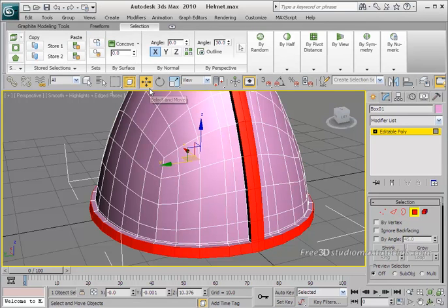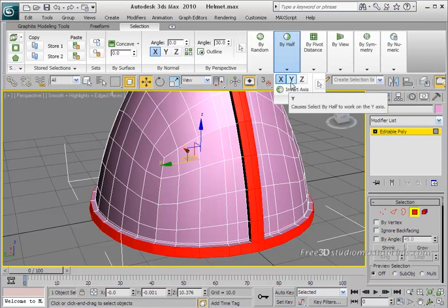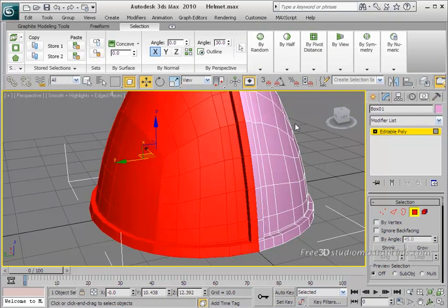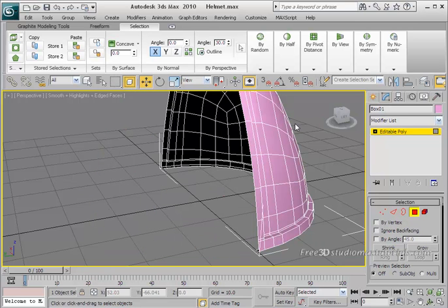We did this in our previous lesson too. On the by half panel, click Y. Just click on this by half panel. Now in this, just click on the Y and then click the selection button. Okay. Now click on the invert axis. As you can see, the polygon selection is inverted. These are the polygons you want to remove. Okay, now press delete.